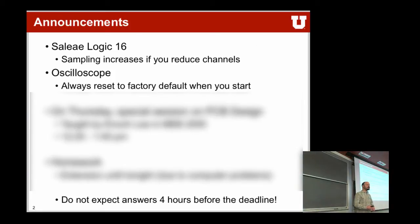A couple more pointers. The logic analyzers that we are using are the Saleae Logic 16. It has a really nice feature: if you choose not to use all 16 channels, but only a subset, it can sample a lot faster. You can go up to 100 megahertz on just 2 channels. I think it's about 25 megahertz if you use 8, and 16 megahertz if you use all 16 channels. So if you need to look at a faster signal, try to reduce the number of channels, and that way it can go faster.